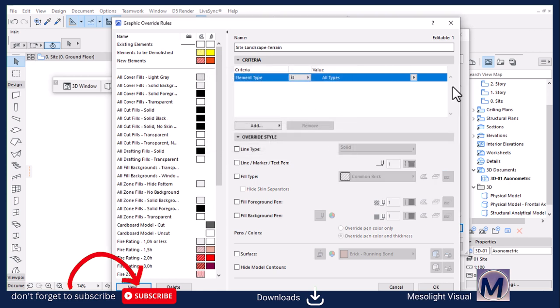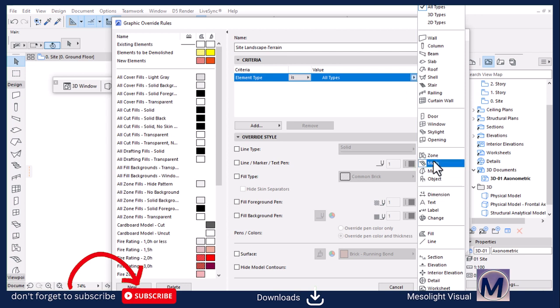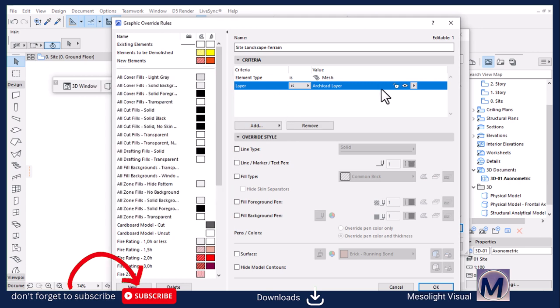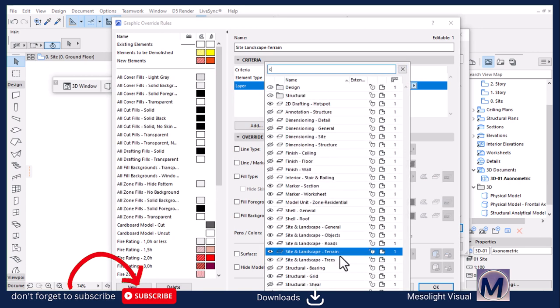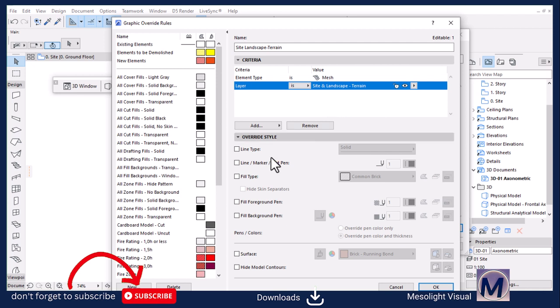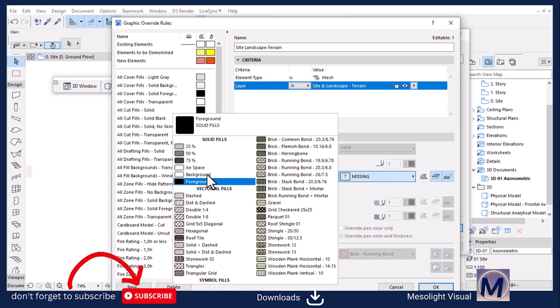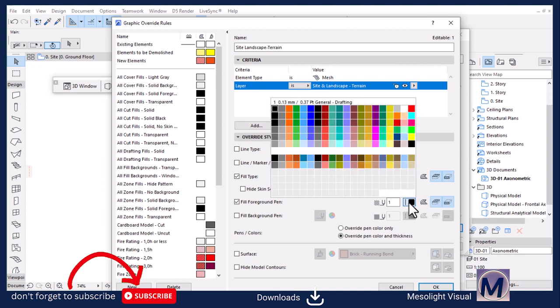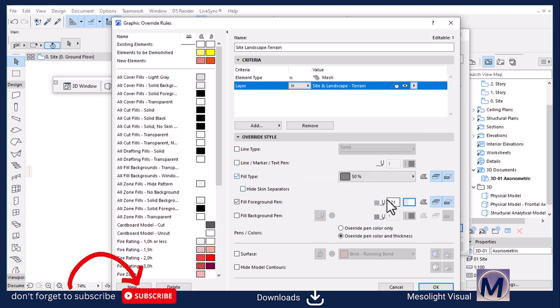And then hit OK. We want the element type to be mesh because it's been created by mesh, and then we're going to add a layer for that, because we have a layer assigned for the site landscape, which is this site terrain. Then I'm going to override the field type, make sure the cover field is selected, and key in the field type, which is 50% field, and then the foreground pen. Make sure you also override the foreground, and then change this. We want a white color.